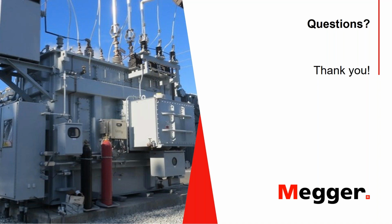In addition, if you do not demagnetize the transformer and you try to re-energize, say you've completed your testing and you forgot to demagnetize, when the transformer is being re-energized, the differential protection schemes might see that magnetized core absorb more current. That might be seen by these differential protection schemes as a fault, and then you would have a nuisance trip. So it's always recommended that you perform demagnetization after winding resistance.